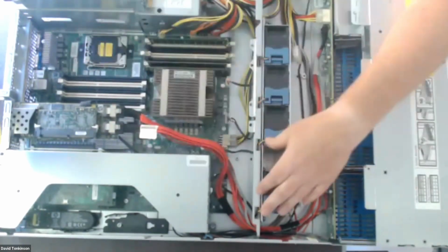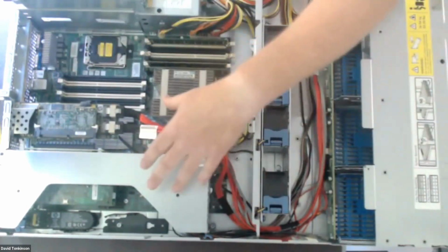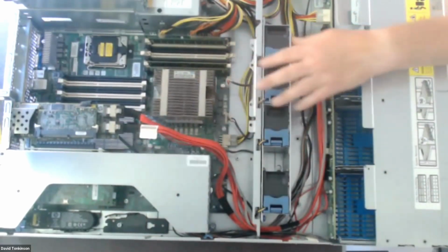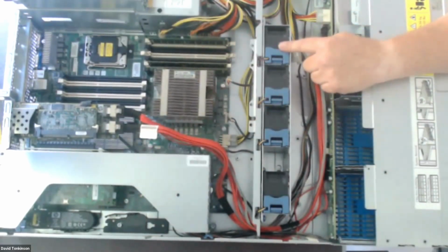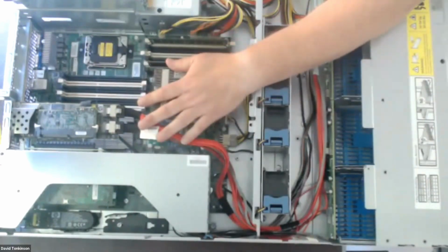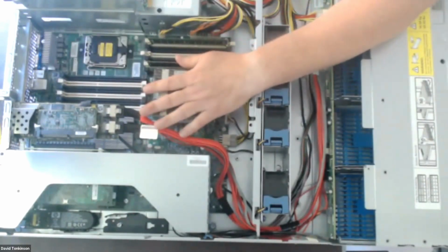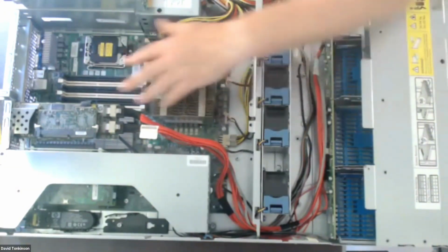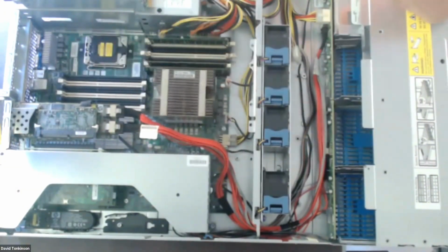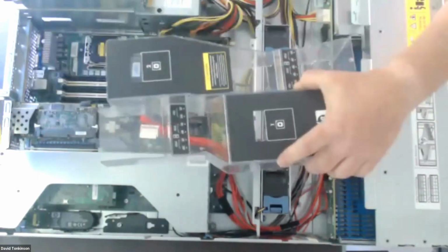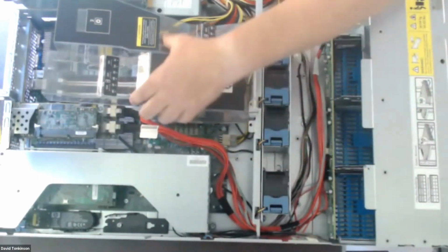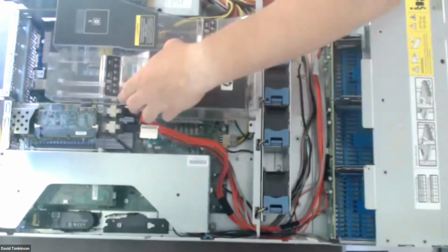The other two are just blowing air from the other locations through the other systems. This allows us to change the speed of the fans to keep the processor cool. So if you're doing a lot of hard work on this system, processors get warmed up, these two fans increase in speed, blowing more air across the processor. This stops the air getting muddled as it gets blown through the system, so it doesn't go round in circles.